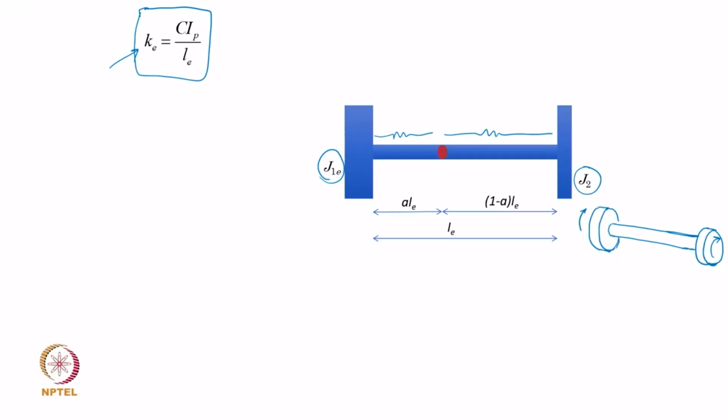Okay. So, that is what happens, that out of the 2 natural frequencies, at the first natural frequency which has a 0 numeric value, both the inertias simply rotate. So, you can imagine that the wheels on the axle or the entire axle itself is rolling without storing any strain energy, or the 2 bogies connected by a flexible spring, the 2 bogies are simply moving together without the intermediate coupling being stretched anyways, right. So, it is a rigid body motion. In the second natural frequency, these 2 inertias move in opposite direction.